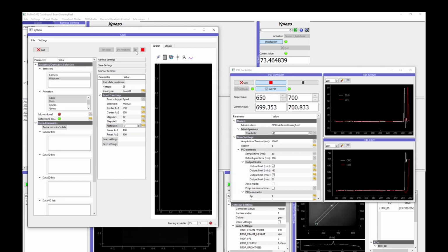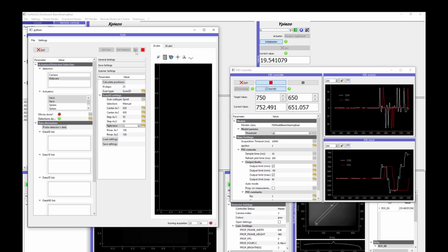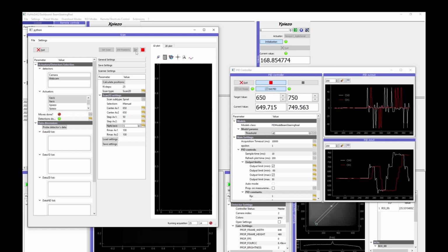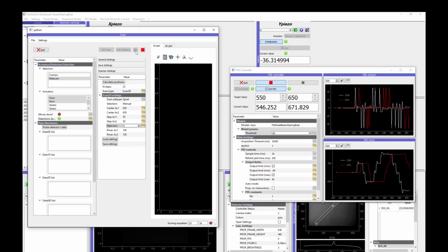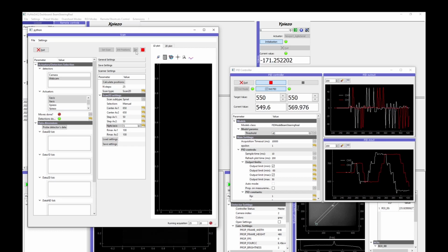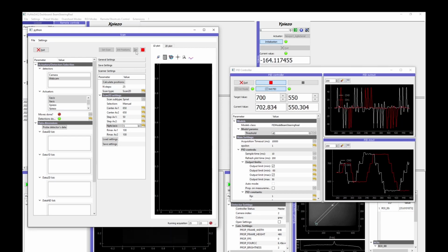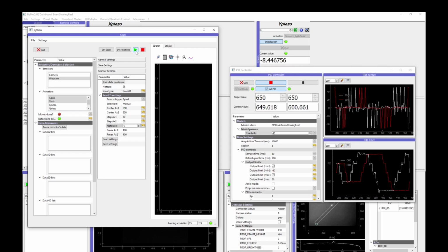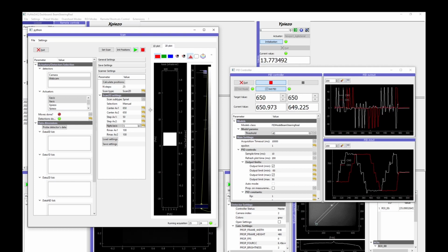Okay, so the system is telling the PID loop to move around, and when it has achieved the right position, it does the measurement. Of course, here my measurement is very quick, but you can imagine that it would be very useful if you have to do a measurement that takes hours. And during those hours, you want your system to be as stable as possible, whatever happens in your environment. So that would be the perfect solution to do some usual scanning while using a PID stabilization loop on your system. And we can check here on the system that it did the right thing.